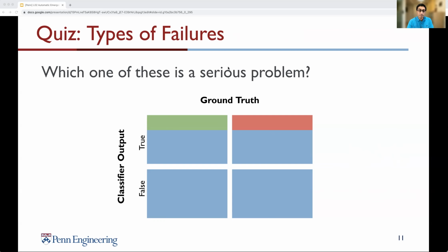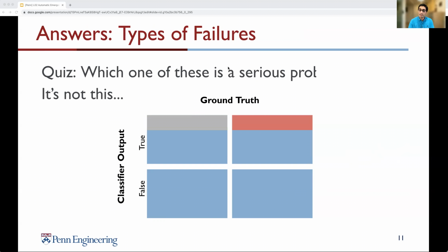For AEB, first let's look at the false positive. It's an error in our binary classifier where it detects a critical object and brakes, but actually there was no critical object. This is aligned with the engineering incentives to make the car safe. It's better to be conservative and have a few false positives because we want to err on the side of being safe. And if there is a slight doubt whether the object is critical or not, and we hit the brakes, that's okay, right?